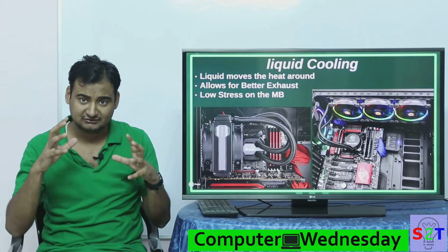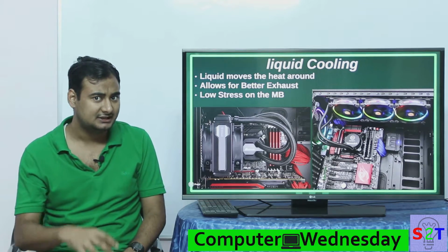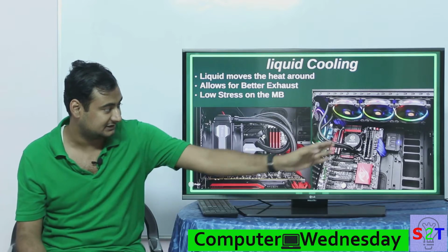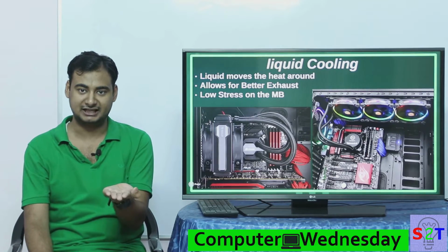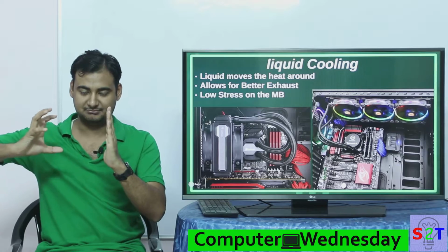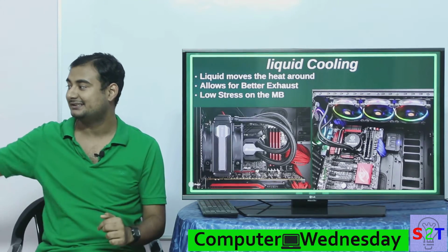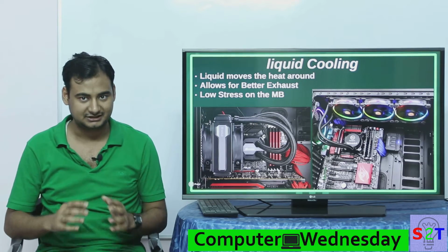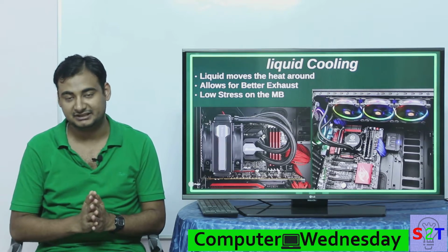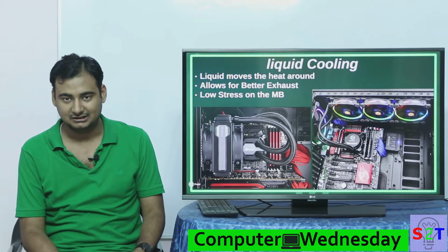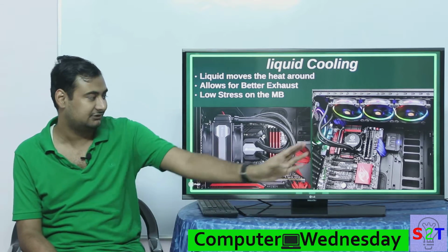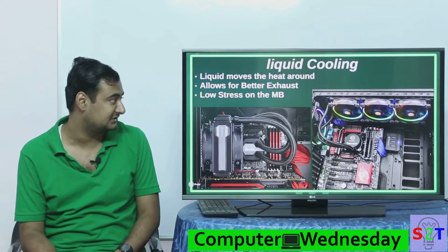And you have to understand, many of those big beefy air coolers put a lot of stress on your motherboard. Basically, as you can realize, we generally have the motherboard not lying down like this. So it's a big heavy block coming out of it. It's putting a lot of stress. Now it's not an issue, but you have to be mindful. It might become a headache if you have a really big powerful CPU. So liquid cooling starts to make more sense in that sort of scenario.